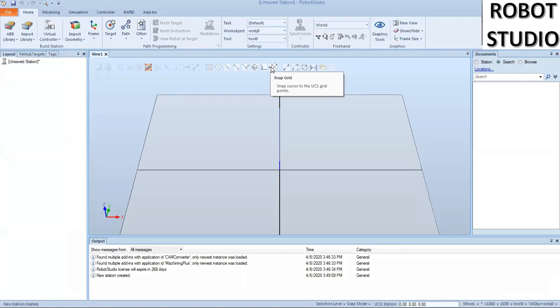If you have your robot designed in this virtual station and the work object set up correctly, you can create programs and modify the code via templates or a text editor. This process is also good for reach studies, cycle times, and for creating part modules that can be edited later. For the sake of this argument, I'm going to create a robot cell with a welding torch and skyhook positioner, also called a tilt-turn system by other integrators.